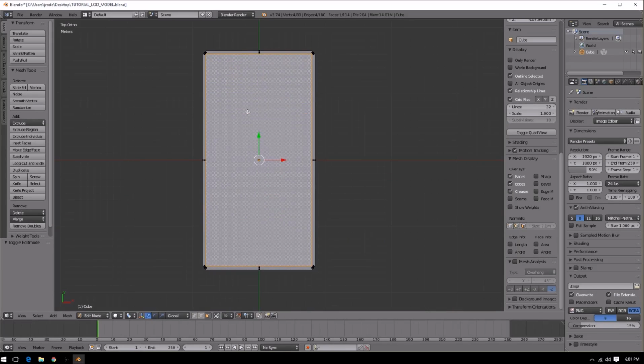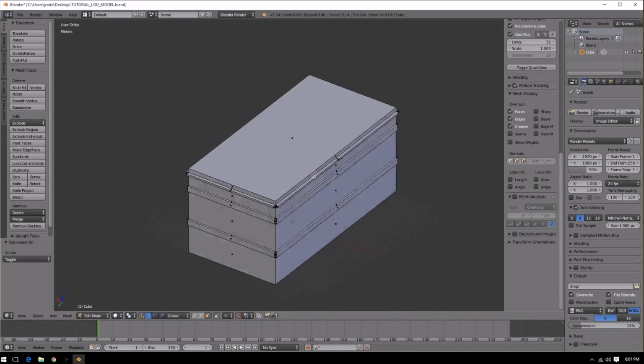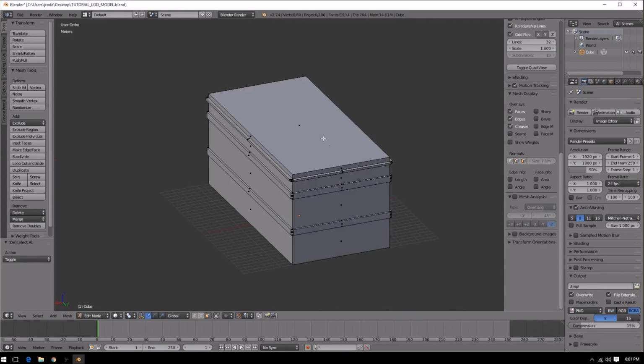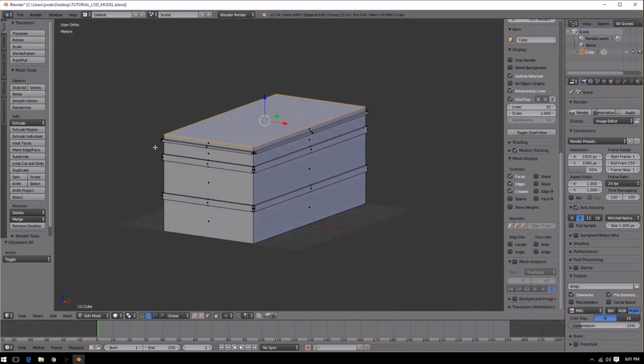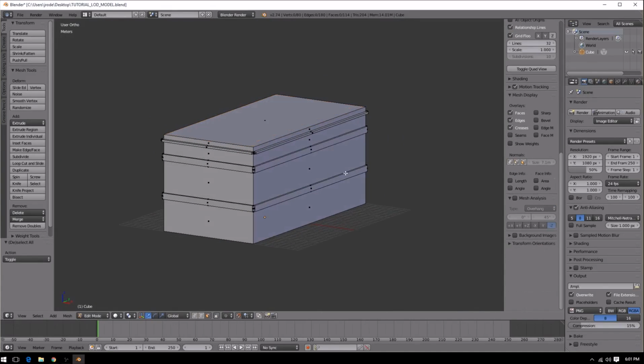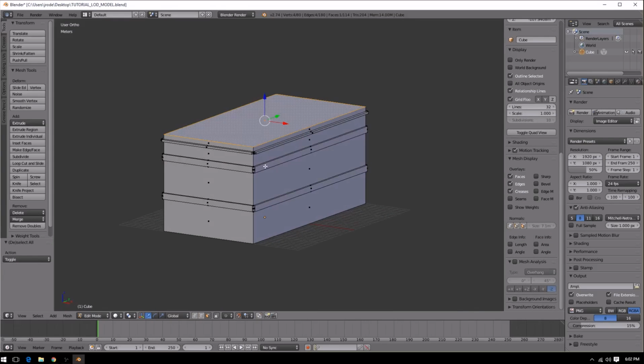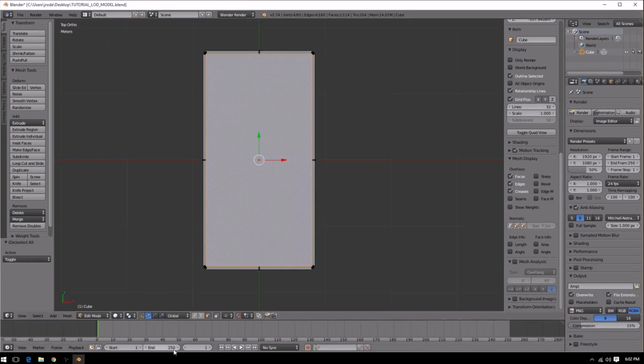And after selecting this face, now remember, you want to make sure only this face is selected. So hit wireframe mode or scroll around your model and make sure nothing else is selected. You can also hit A to deselect everything while something is selected, and then re-click it to make sure it's the only thing. But hitting 7 to go back in the top view, I'm going to do something called Inset Faces. On the left toolbar under the tools, about midway through, you're going to see Inset Face.